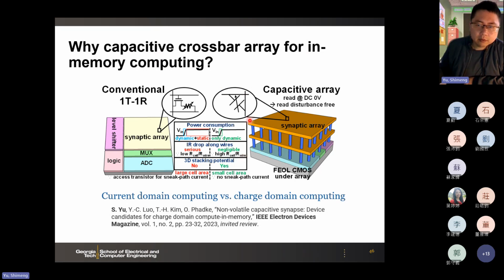So here, let's say what we have is a capacitor in the crossbar array. Compared to the RRAM theory last lecture, where we showed the chip we designed with TSMC RRAM technology, which is 1T1R, and then we do the current summation along the column. But then we figure out some challenges in the current domain computation, because if you sum up the current, then you will spend static power.